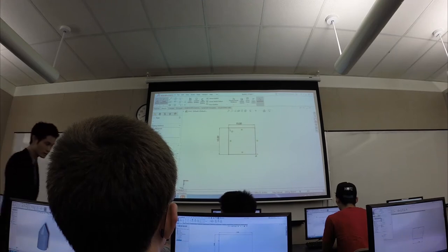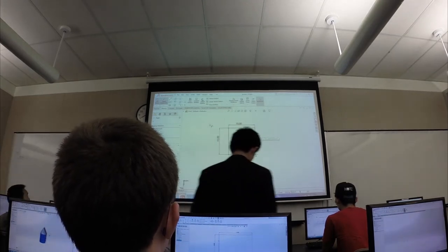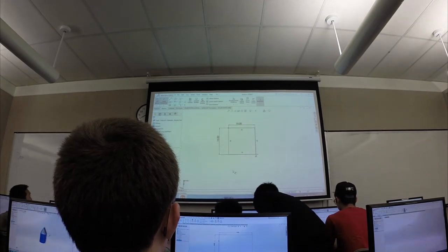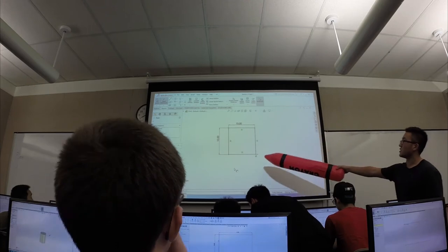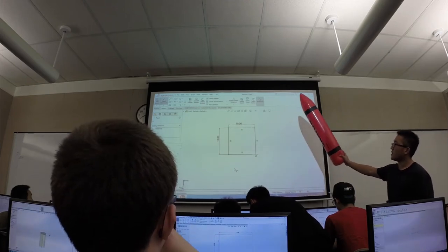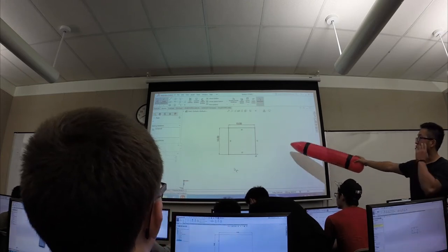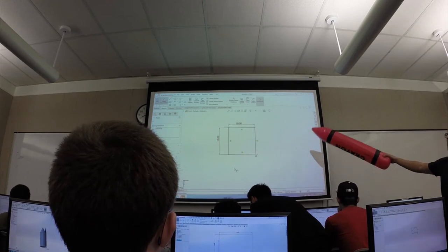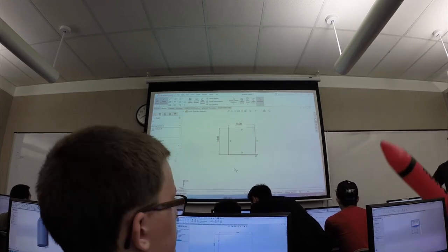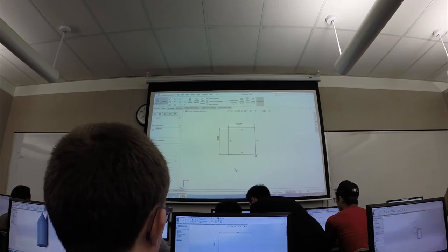I could drag on a point and try to drag it around like before, but you'll notice that it doesn't go anywhere, because these numbers are binding it. Also, this is all black because it is currently fixed to your zero coordinate. If your box was drawn somewhere arbitrarily in space, without referencing the zero, it would all come out blue, because you could still technically drag that box around, and it's not defined to a place in space.